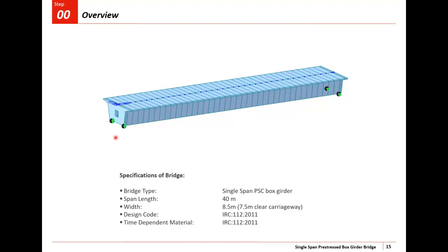Here moving load analysis was also done, but we have simulated the entire bridge model by a single line. But as I said, when we model as a line, we cannot get the stress in the depth of the section, like detailed stress concentration and other things like crack propagation. So for doing crack propagation and the detailed stress strain analysis, we exported this line into a solid for MIDAS FEA.